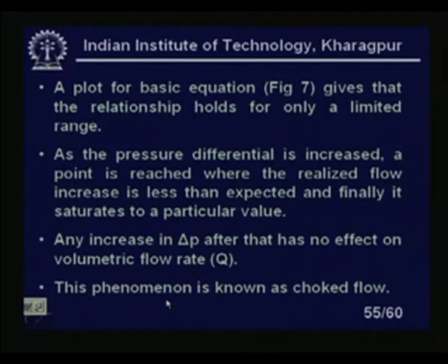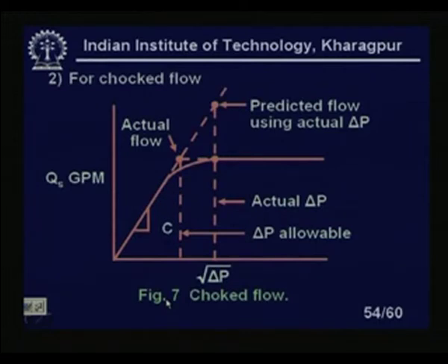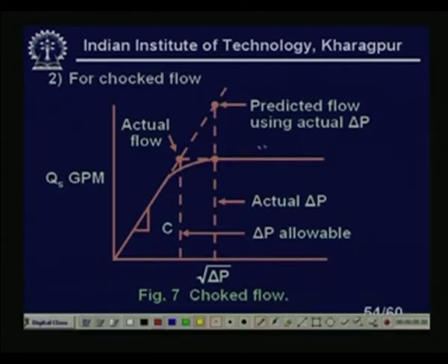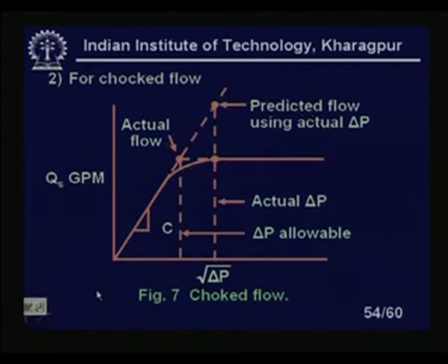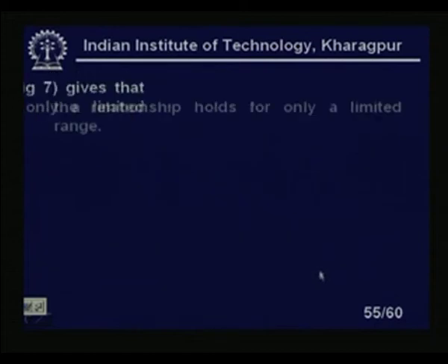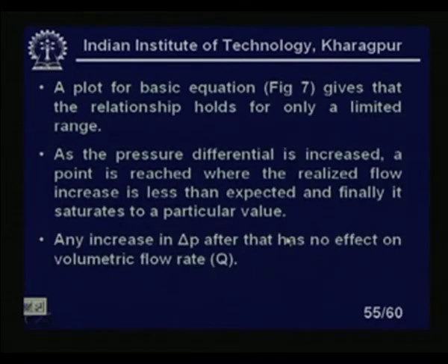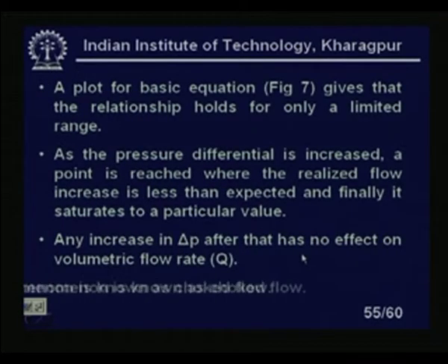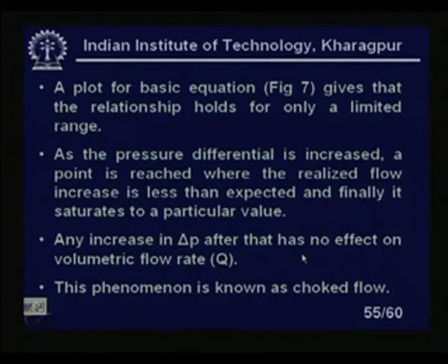This phenomenon is known as the choke flow. This portion is what we are calling the choke flow region. Even though I am increasing the pressure differential, the flow is not increasing, it is getting saturated. Clear? So, this phenomenon is known as the choke flow of the fluid in a control valve.